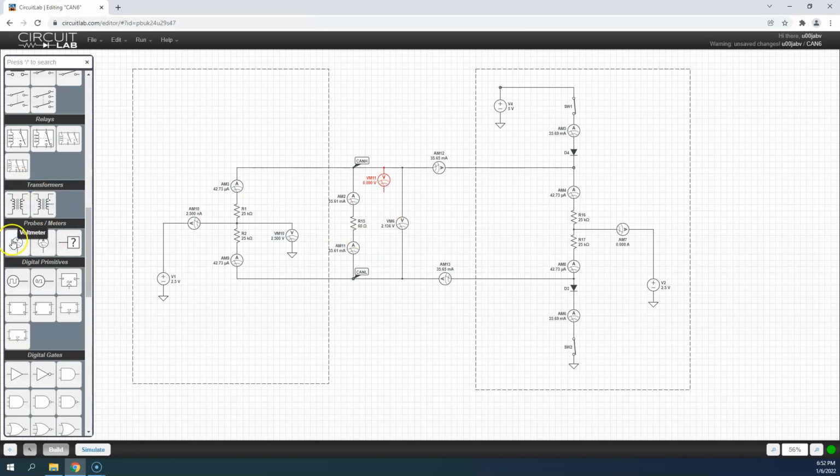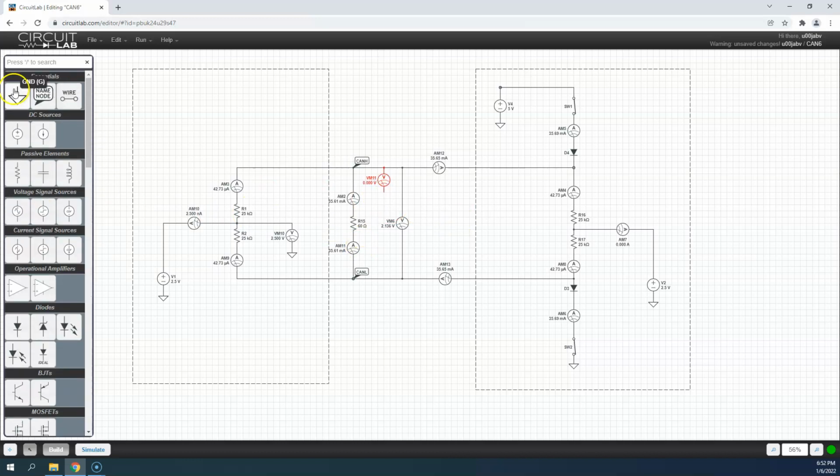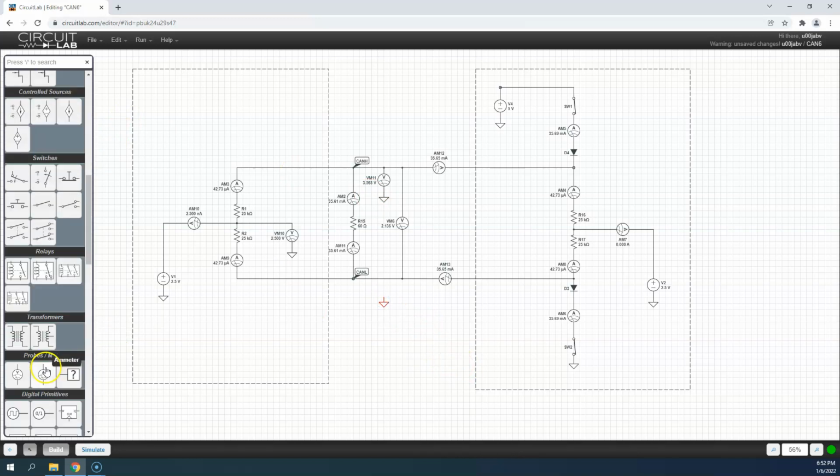If I took my multimeter out and I put it on the CAN bus now, we know that this is going to be, what, 3.5 something. The other side is going to be 1.5 something or 1.6, right? So put this on there, put that on there. Whoops, got to make it touch. I got a bad connection on my meter here. There we go. Just like a real one, right? So 1.432 volts. We can see right here, this is 2.5 volts.